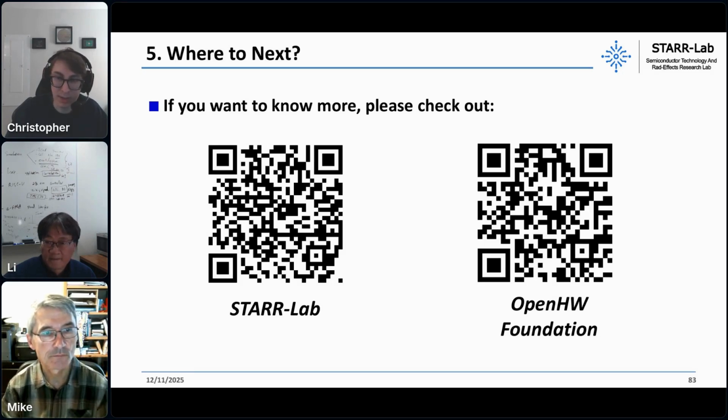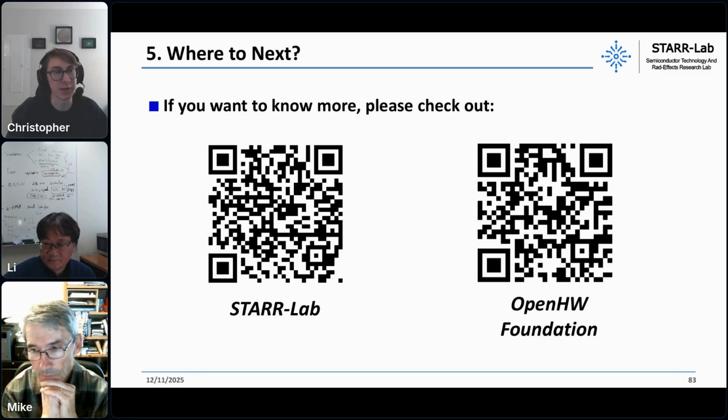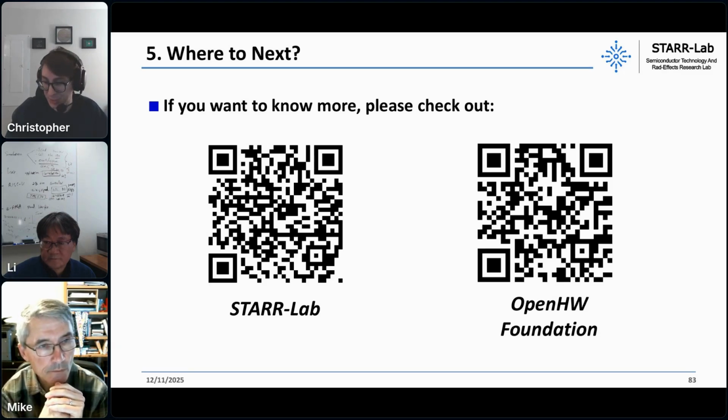Yeah. So, in terms of cost, you would be paying a little bit more in the sense that the total chip area would have to increase a little bit, right? So you have to pay for that extra die area. If you're talking more from a commercial standpoint, a space qualified rad hardened chip compared to just a consumer one is always a big price increase in the industry.